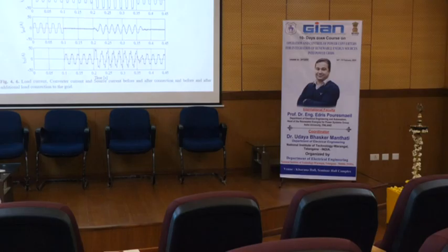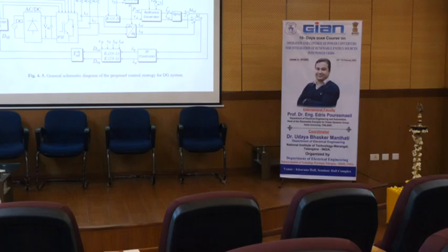So, by this ILQ reference, we compensate all the reactive power in both fundamental frequency and harmonic. So if we get back to simulation, you see that our reference current in Q axis is all ILQ.